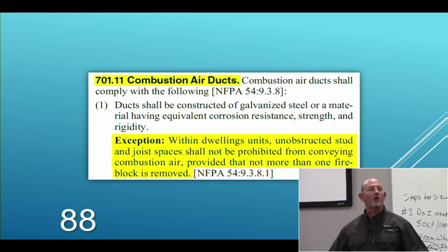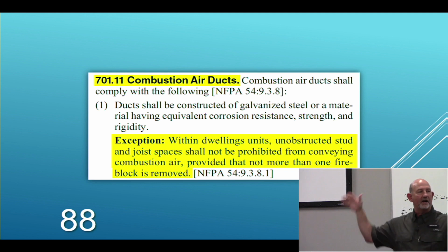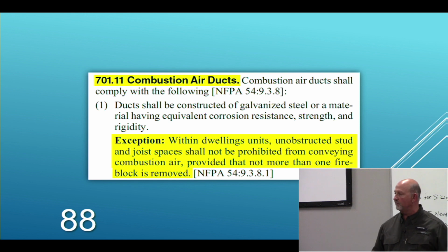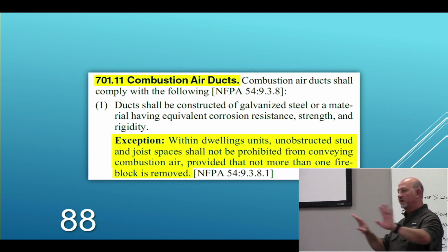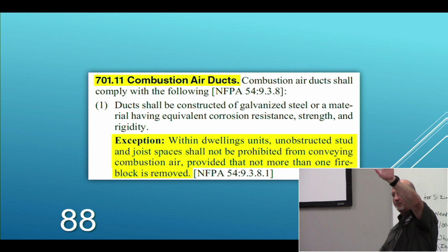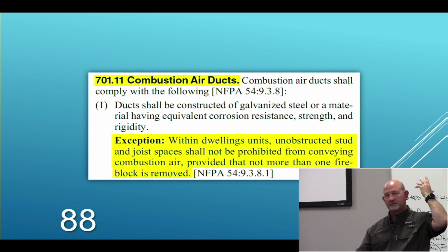And then when it's cold in here, that cold air settles, creating a static pressure on the floor, pushing that air out the lower, creating a vacuum in the room, pulling the air in the upper. Does that make sense? So again, if I had a hole in the top and bottom, do you agree just recirculate the same air theoretically? Right? But by doing two, I'm pushing out here, pulling in there, pushing out here, pulling in there. Right?